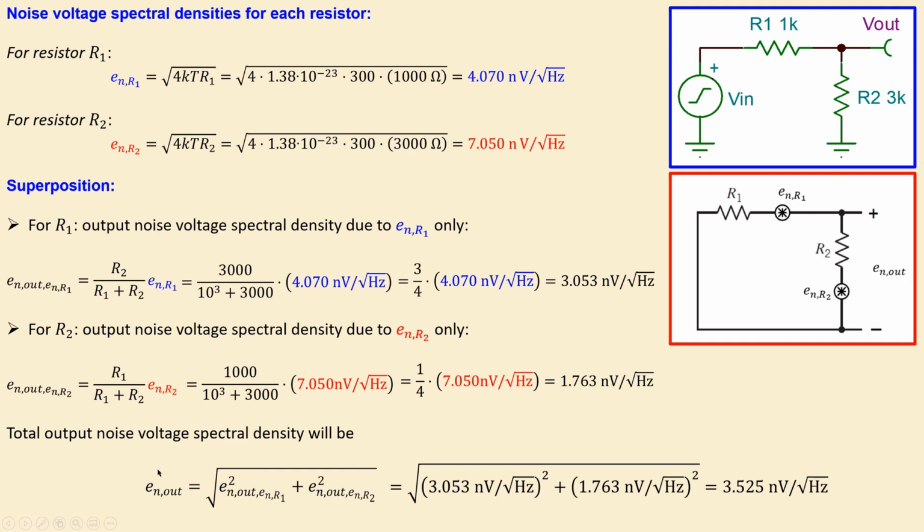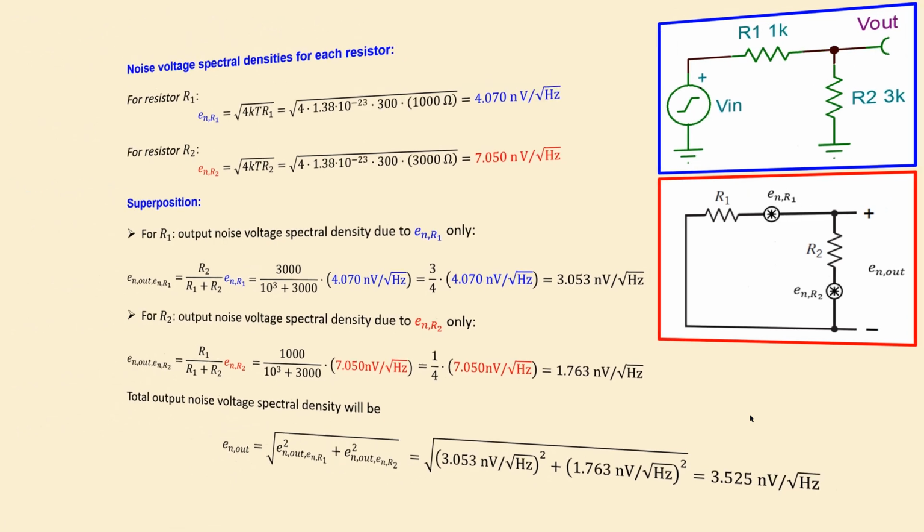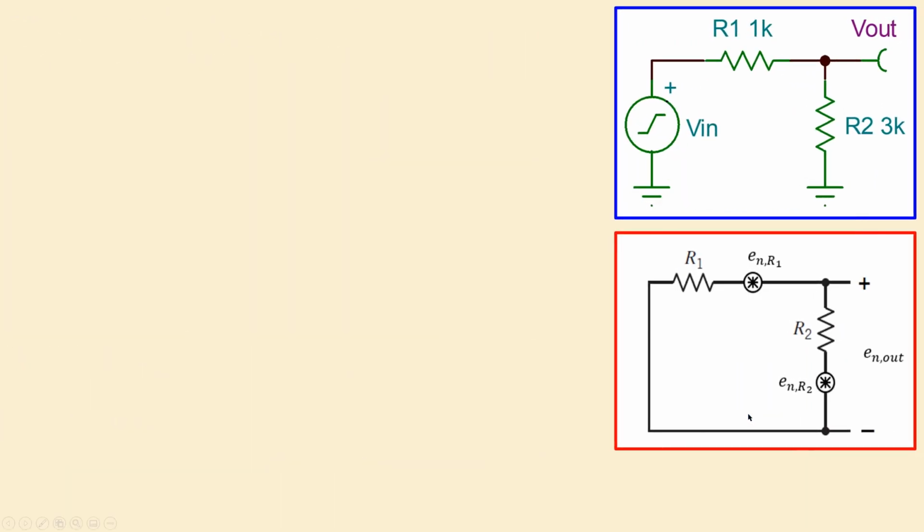We will use this, of course, and you will already see that this is frequency dependent, and that will be, of course, then used to determine the actual RMS noise voltage at the output. So let's look at the following situation, but let's also look at it in a different form, because there is an alternative calculation for this one. So it's not only using the model where you have the R1 in series with your noise voltage spectral density.